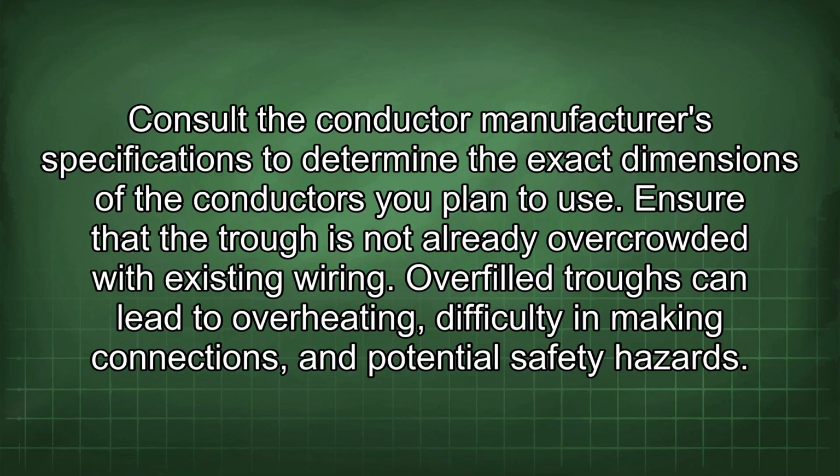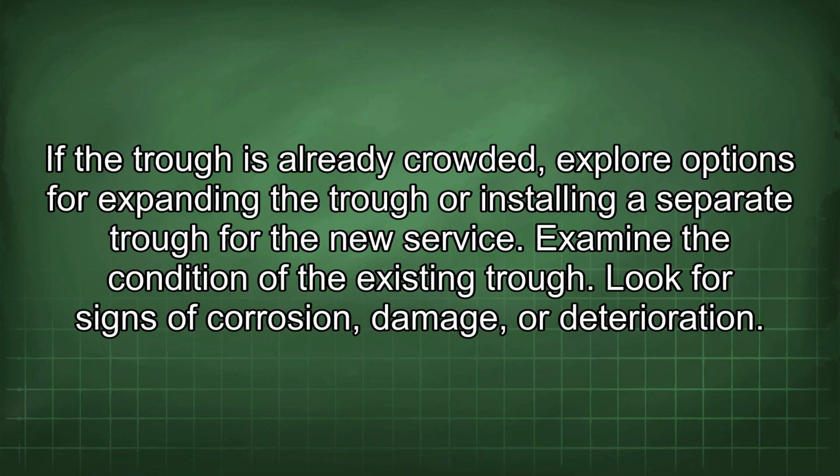Ensure that the trough is not already overcrowded with existing wiring. Overfilled troughs can lead to overheating, difficulty in making connections, and potential safety hazards. If the trough is already crowded, explore options for expanding the trough or installing a separate trough for the new service. Examine the condition of the existing trough.